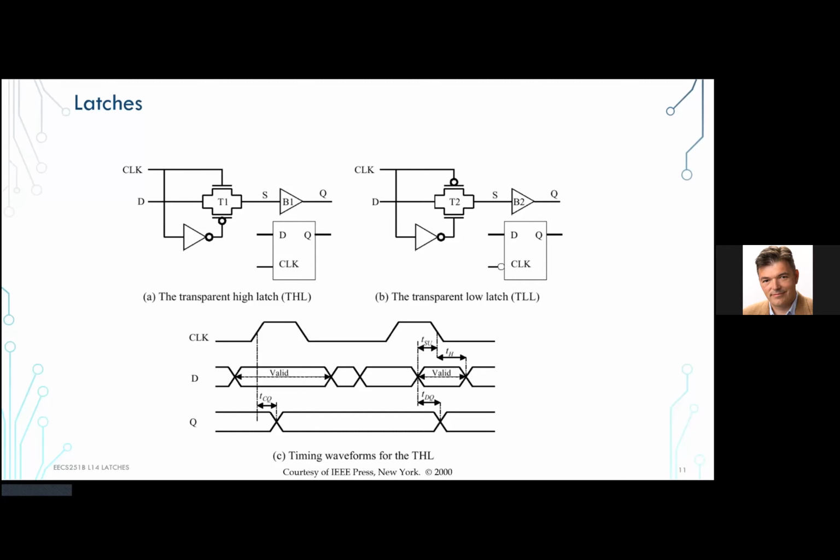If you're doing something up to the G5 class, I think G4, Mac G4, it was possible. You have a big design team and they do it for a simple core processor. But then things became so complicated that it was not possible. We would have needed design teams way bigger than companies can afford. So that path has been abandoned, and all the latches now have a driver in front.